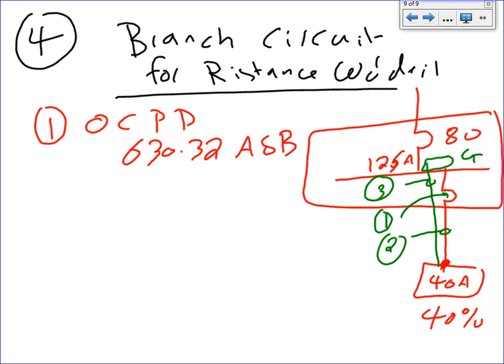Good point. You might be in a situation, guys, where the welder would not start with a 200% device, because every time you start it you're arcing, making a short circuit, and it will trip. So they allow you to oversize the overcurrent protection right next to the welder to 300%, versus undersized at the feeder. That's the only thing I can come up with. But both of them are in series though, so they're going to be seeing the same current.